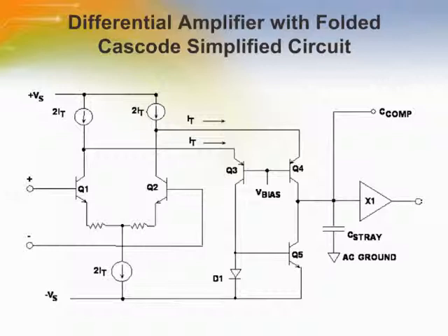A typical example will show that the small signal unity gain bandwidth product can be 20 to 50 times the full power bandwidth. Therefore, most VFB designs of this type actually require emitter degeneration resistors to reduce the input stage transconductance and hence reduce the small signal bandwidth, adding stability and making the unity gain bandwidth product more in line with the full power bandwidth. The emitter degeneration resistors also serve to linearize the input stage GM transfer function and thus lower distortion.